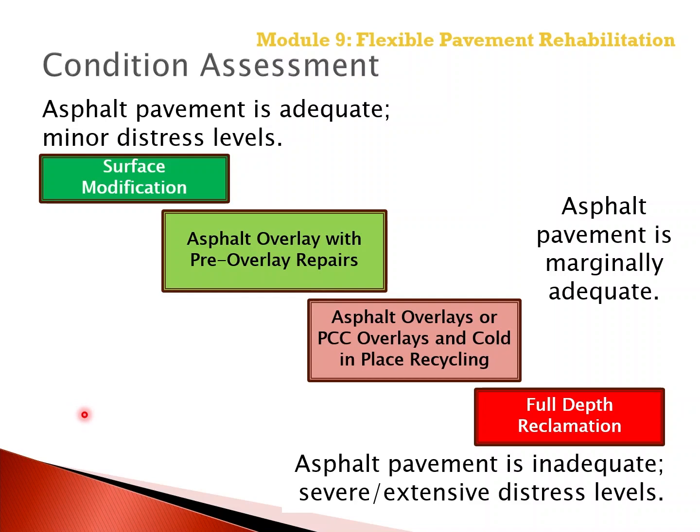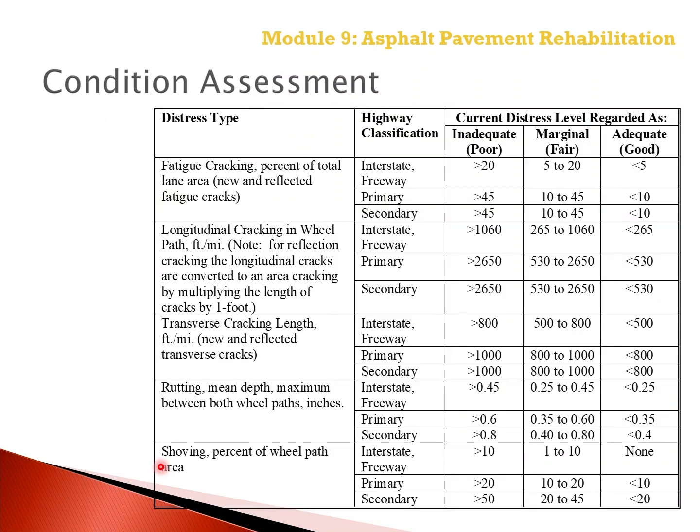Pavements that are considered totally inadequate and have severe extensive distress surveys may require full depth reclamation or very thick asphalt and or concrete overlays for ensuring that the observed distresses will not reoccur within the rehabilitation design period.